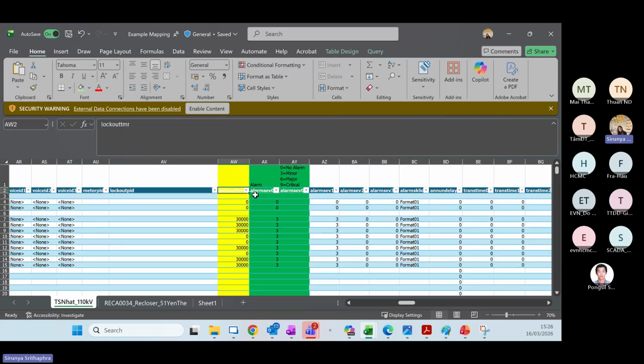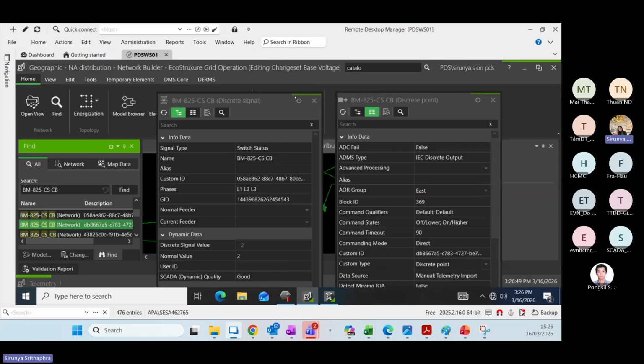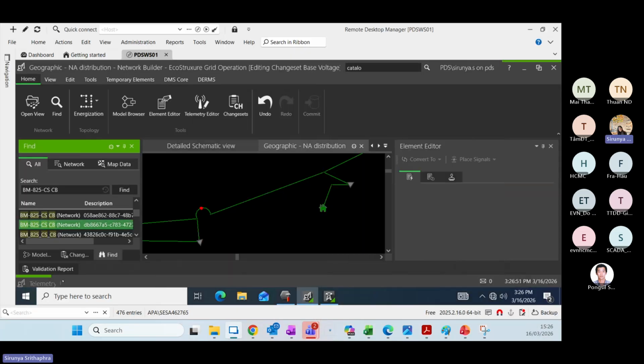Say from the RTU we get one remote point as input; for sending ICCP it could be an output point, so there will be two points, one input and one output for the same signal.